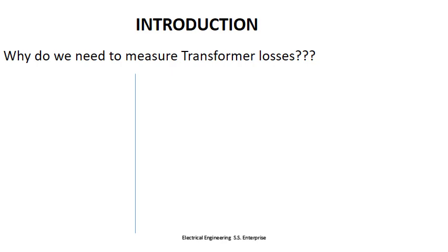The real cost of a transformer for the owner is the sum of the initial purchase price plus the cost of running it for a lifespan of around 30 to 40 years. Purchasing decisions require the right balance between the initial purchase cost and the cost of future losses. Losses are the wastage of energy in the device, which will affect the overall efficiency.